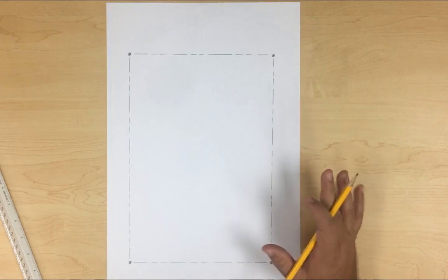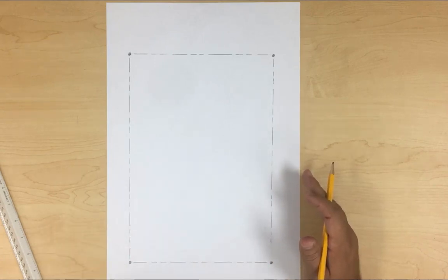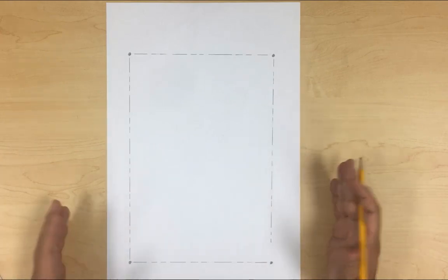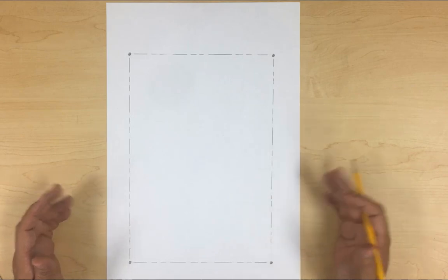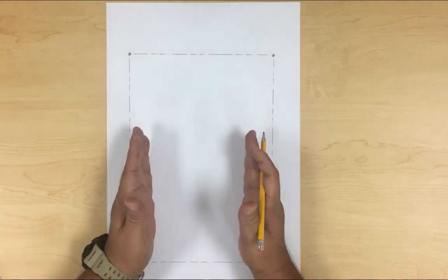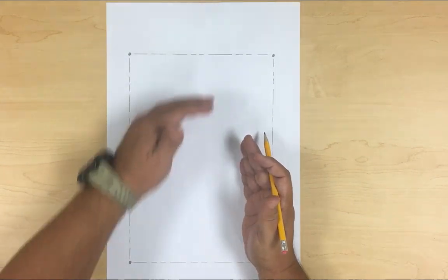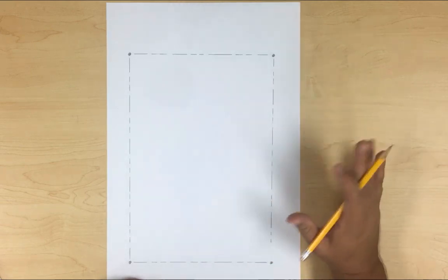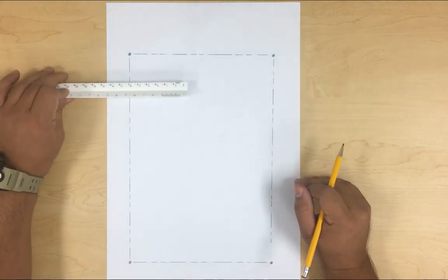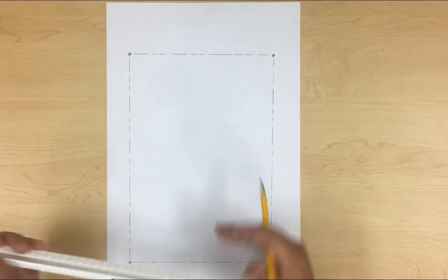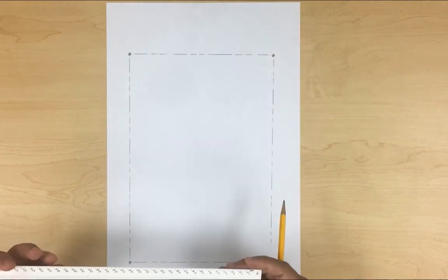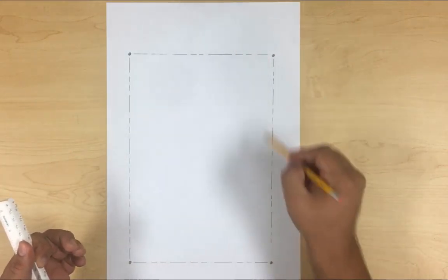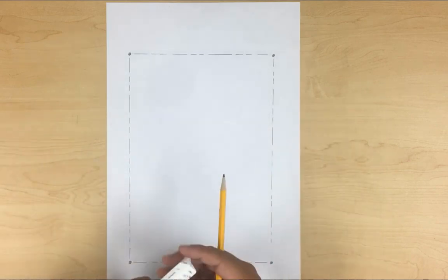From the property, what we need to know are the setbacks. This is going to vary depending on the city and the ordinances. We're going to do just the common ones. I believe the most common are 7 feet from the sides, 10 from the back, and let's do 20 from the front. Again, these are going to vary. Now that we know the size of our property, what do I need to respect so I don't put my structure on a piece of land that I shouldn't?